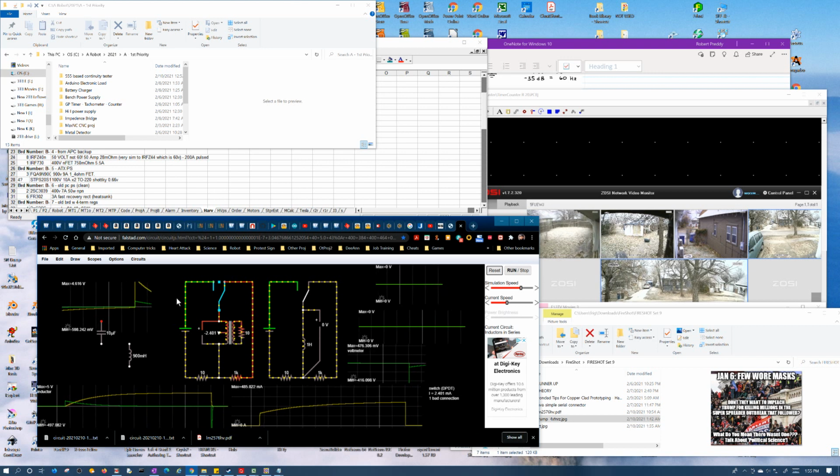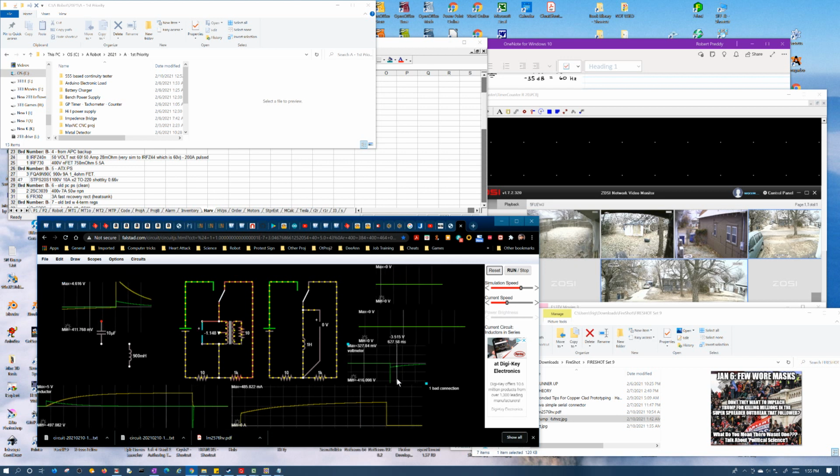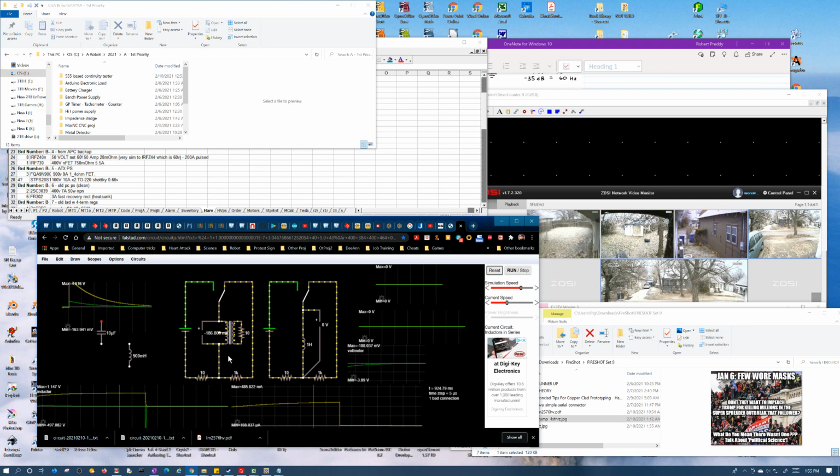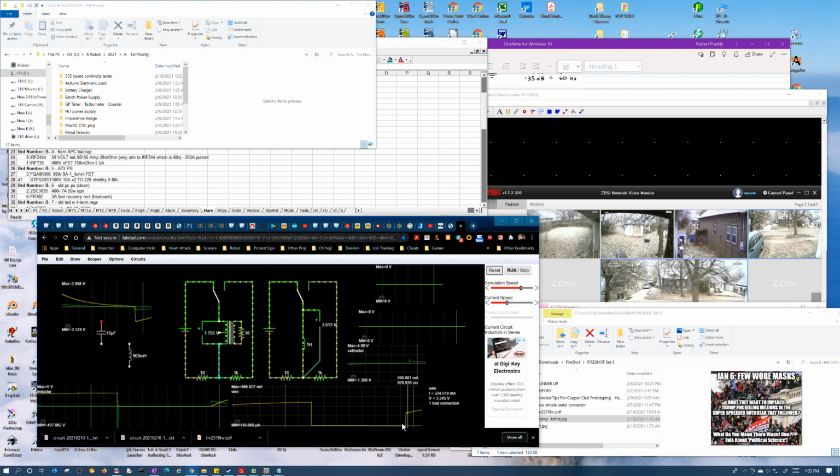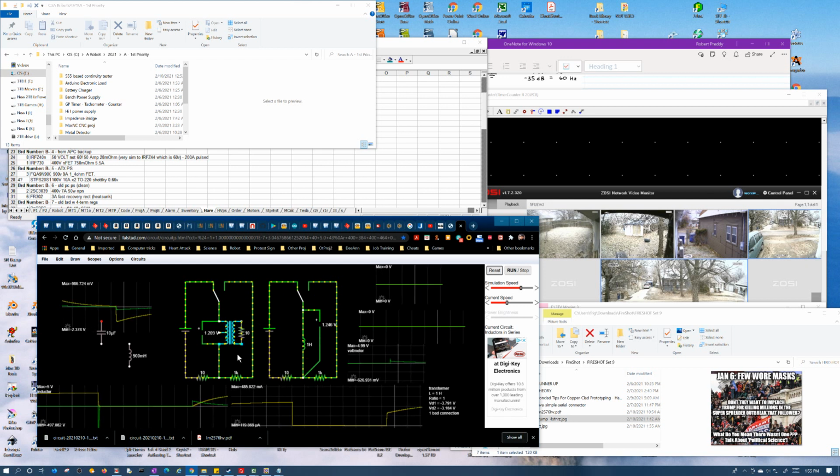Like I said, we dump it, but you still want to see about 5 volts even when it's dumped. Now here, I guess we did still see a big spike. So again, it just goes to show you, if these things change state, yeah, you can see some really big voltage spikes. You see this starts to charge up really fast, and at some point it's running into the resistor. So that's probably an artifact of its modeling, I would imagine.